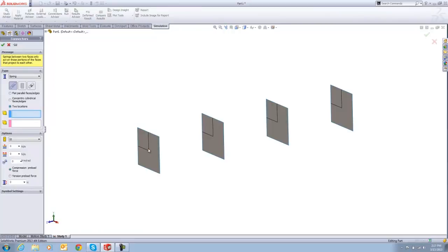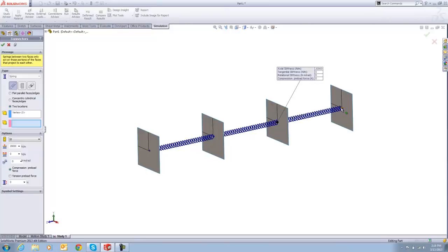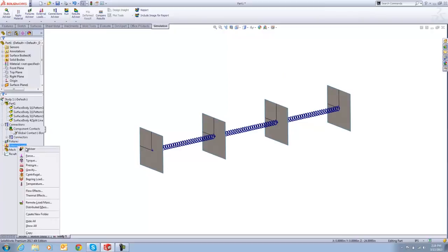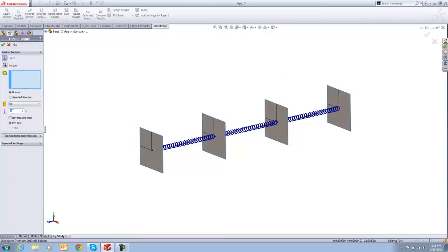Leveraging the vertices that I've created, it's very simple to attach those vertices and apply each of our spring stiffnesses. And we'll thumbtack that down so that we can easily and quickly grab the remaining nodes. And last but not least, the third one is also 10,000 newtons per meter. Okay. Our second node is where we're applying our load, and that's a normal load of 450 newtons. Total, not per face. Remember, we split the faces.